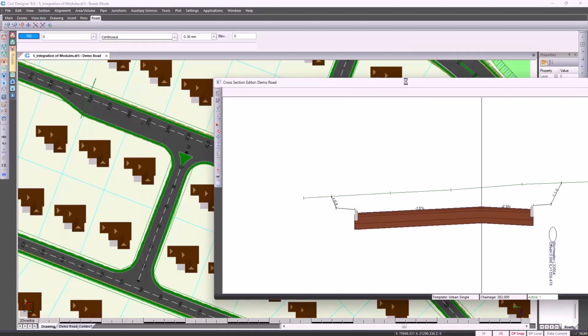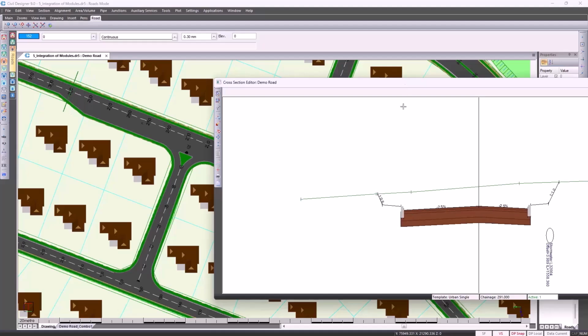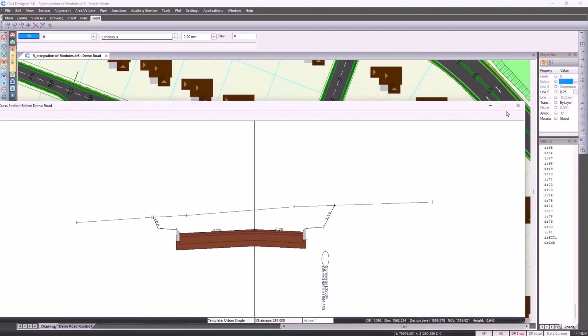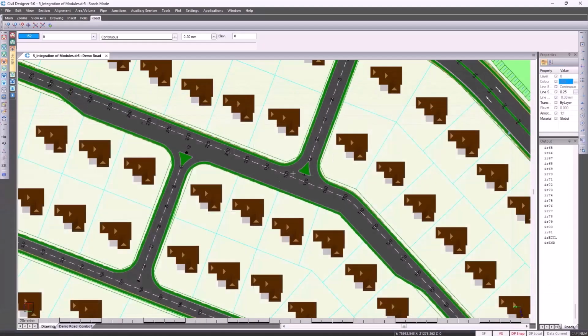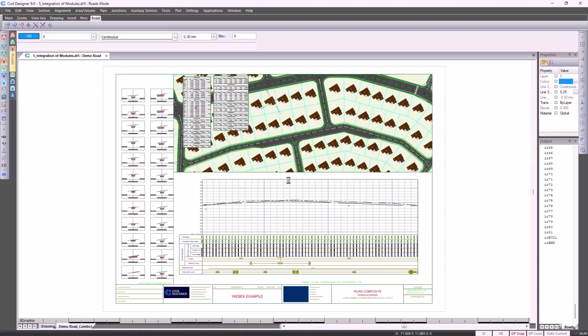And then pressing page down, you'll see how the width reverts back. What it was, it's utilizing the previously specified grade. If we revert back to our layout, the layout will then have been dynamically updated. The layout is now dynamically updated with the two additional junctions or intersections and the additional width on the left.